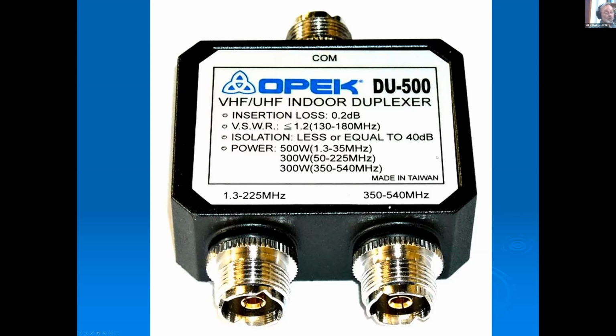The other thing you really have to think about on these devices, if you have an antenna out there that doesn't have a particularly good SWR, that high voltage is going to get reflected all the way back down through this unit until it gets back to your rig or to a tuner to be able to tune that out. So that high SWR is likely to carry a lot of high voltage and can cause problems with it. So this combination here on the bottom, as far as frequencies for each one of these ports or channels, that's pretty common on how they do things these days.